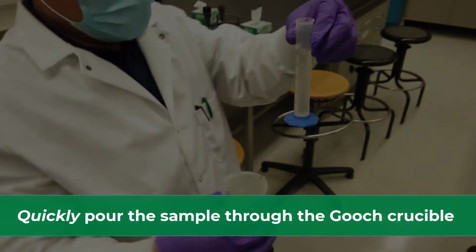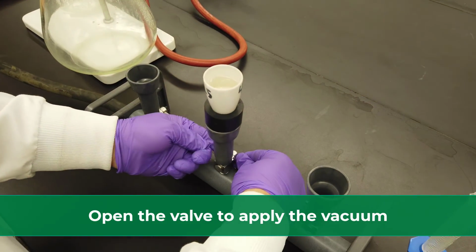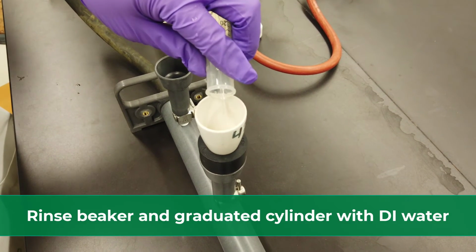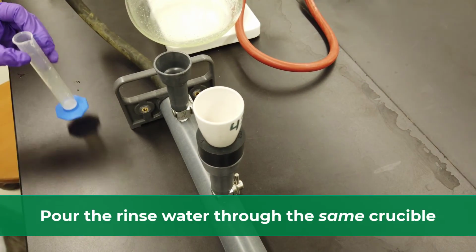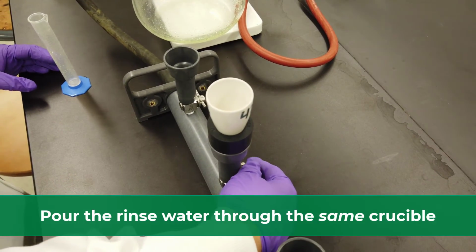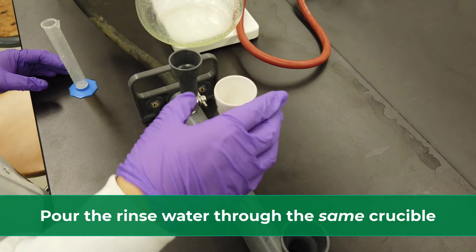Then quickly pour the sample through the Gooch crucible and open the valve to apply the vacuum. Rinse the original beaker and graduated cylinder with a few milliliters of DI water and pour the rinse water through the same Gooch crucible. This should ensure that all TSS particulate from the sample are captured on the filter.